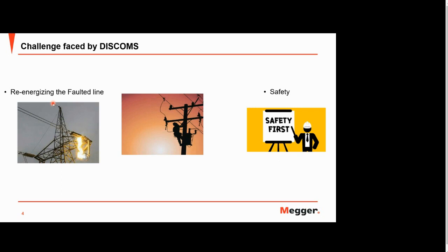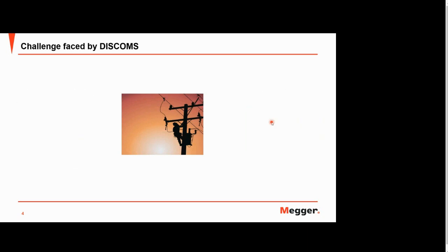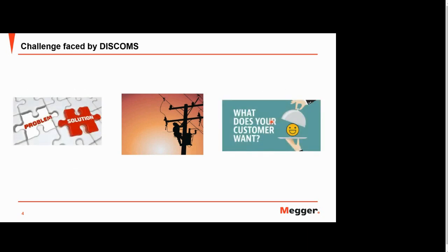Second, when you talk about safety, the high impedance faults, where vegetation is touching your plant, branches are touching. All these things again cannot be detected at a very, very early stage, right? So in all those things, safety has been compromised. So most of the distribution networks have been suffering from this type of problem, and this was always a huge challenge for the distribution companies, how to solve it.